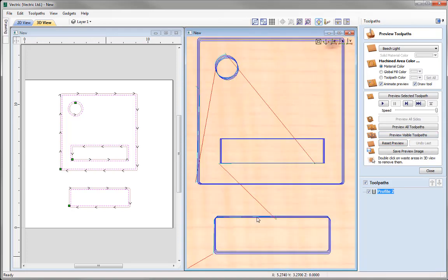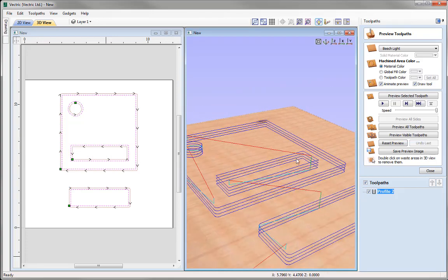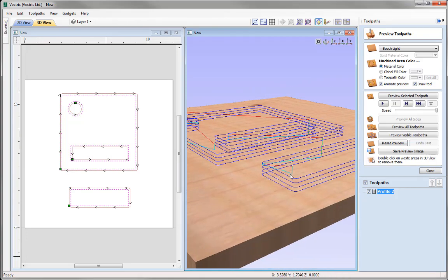And so if we just zoom in over here and take a look at the actual toolpath, you can see this aqua line, which we mentioned earlier, is the ramp line. You can see it's coming in and it's travelling over the 1 inch distance that we specified until it meets that pass depth, and then it's going to go and cut the part out, and then as it approaches the second pass, it's going to ramp down again by 1 inch smoothly into the pass depth and then cut the second pass out, and it will do the same for the next 2 passes.